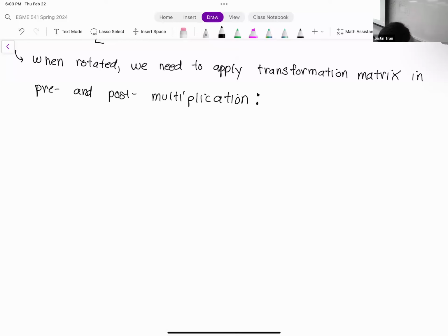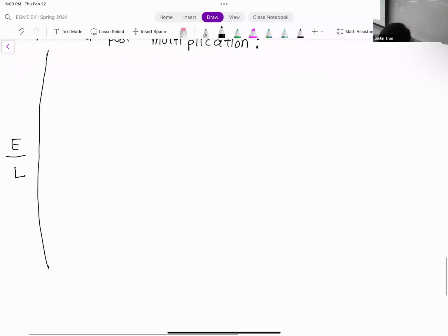So our element stiffness matrix. So I'm going to factor out an E over L. Okay, so that's going to help us out a little bit, just save us a bit of writing. Okay. And then we're going to have one massive thing. All right, so I'm going to write this in the same style as the previous two matrices, and so I'm going to rely on the symmetry here. So I'm just going to write in kind of the top right section of the matrix.